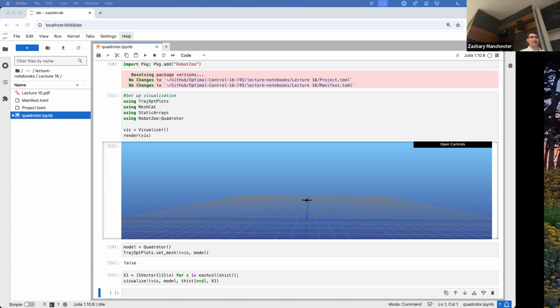LQR is not going to do a bang-bang thing, but where the bang-bang thing would come in is if you have really huge errors and you're running an MPC controller that can reason about the torque limits. It's probably going to slam you up to the torque limits in some of that recovery maneuver, and then get you back on the rails.